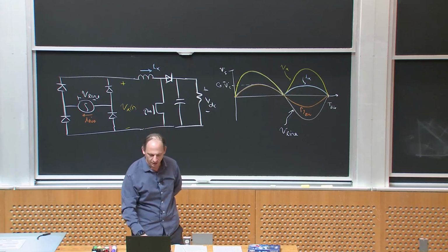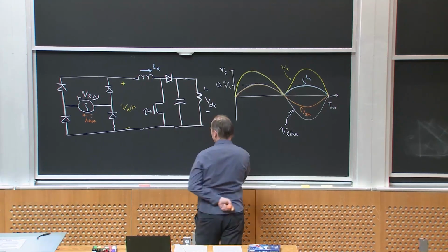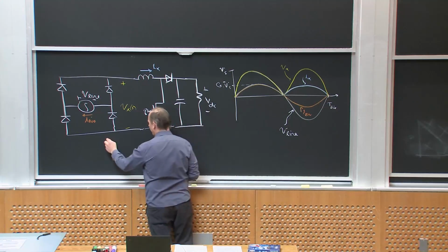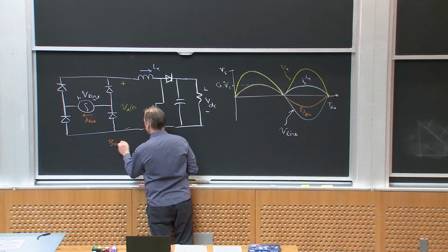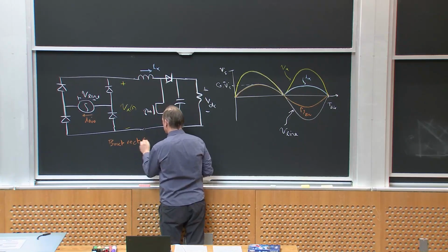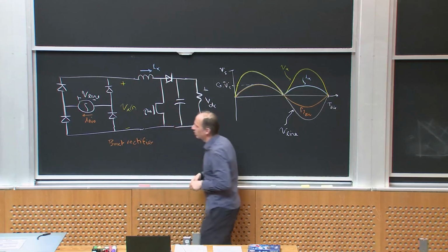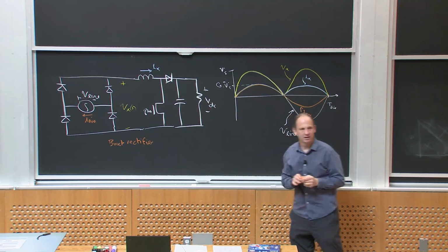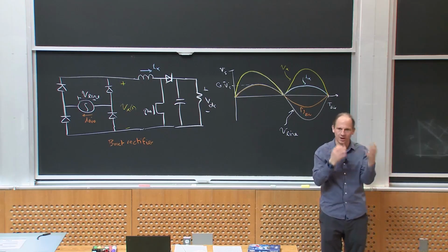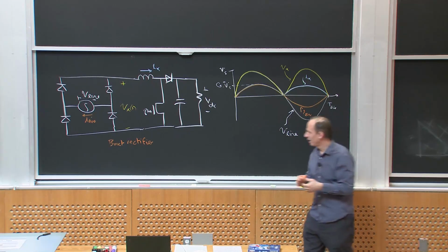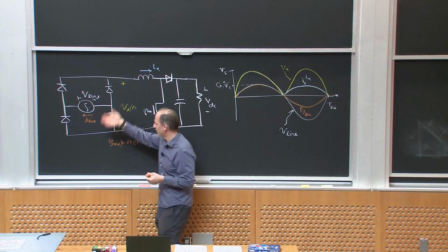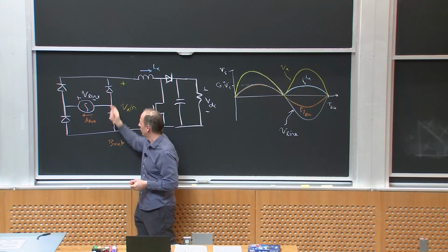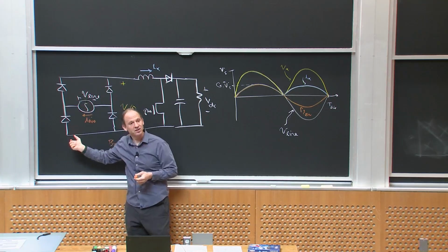Now this kind of boost rectifier, this would be called a boost rectifier, is very much in the spirit of my full bridge. I just don't have to worry about all the phase shift. Now, that said, it can only rectify. Power is only going to flow this way because of these 4 diodes. That's the price I've paid.